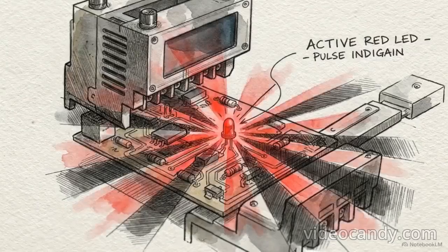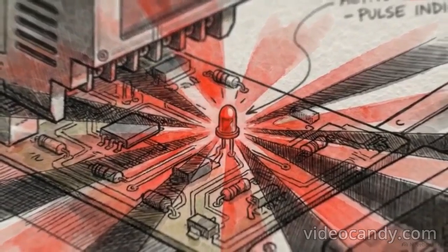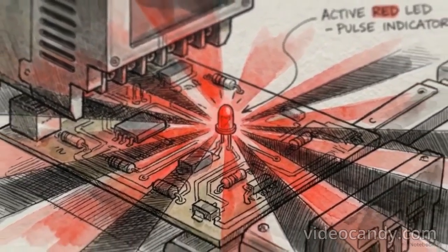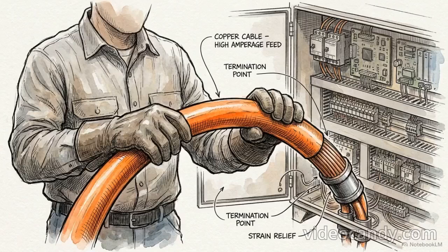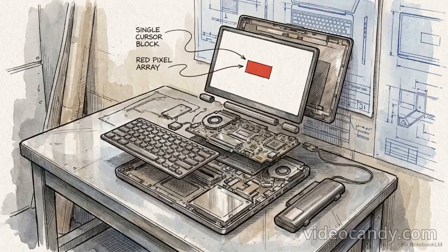You've verified every physical connection. The cables are intact, terminating resistors measure correctly, yet the control panel flashes a relentless, blinking red bus fault. When a PROFIBUS DP master fails to recognize a slave device, the immediate instinct is to blame the copper wire. We look for short circuits, electromagnetic interference, or degraded connectors. Most of the time, the physical layer is perfectly fine.